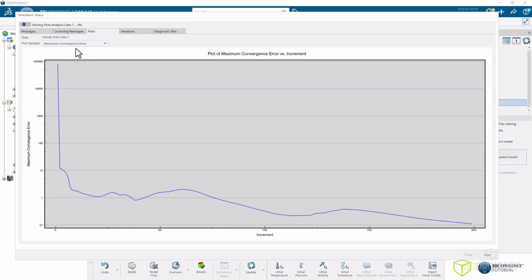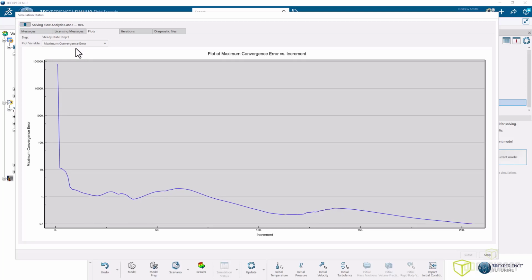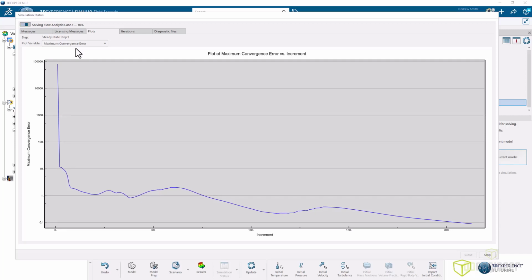Another possible scenario is where I input the flow down the pipe perfectly, or really close, so that when the solver starts solving, it starts with a really low actual error. So when it tries to reduce those residuals, it can't. So you have sort of a stubborn solve.